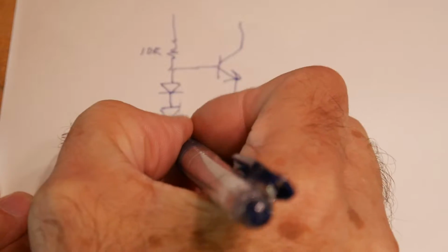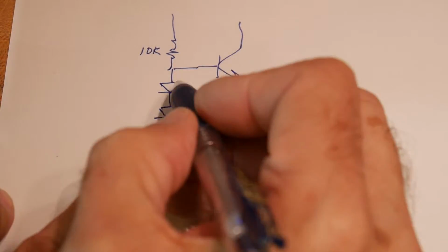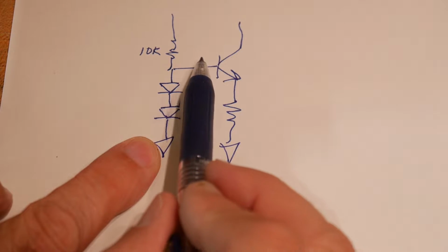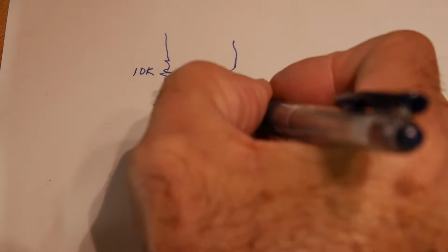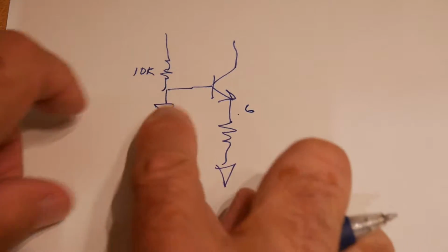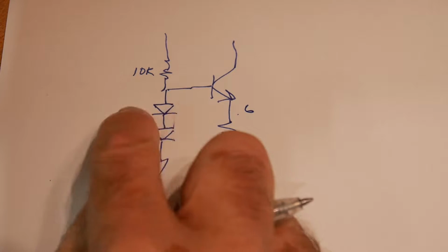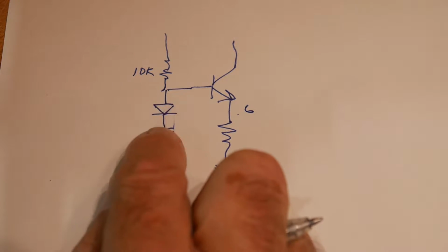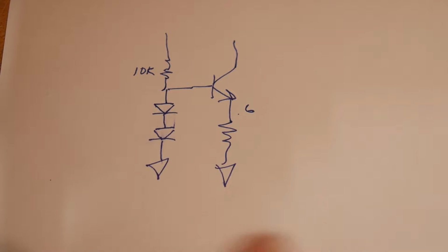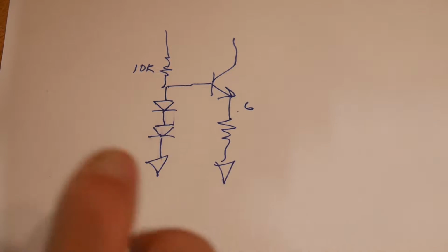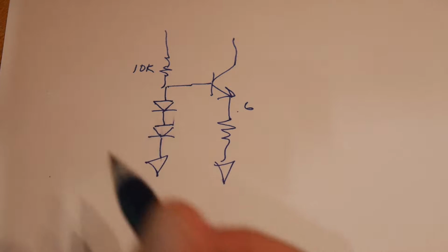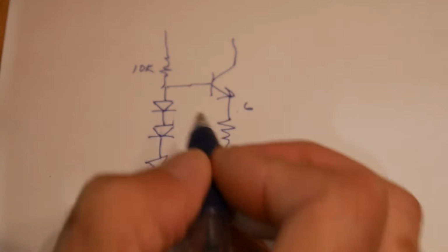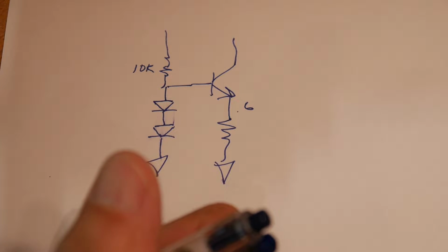So in this particular case, we're going to be putting about 1.2 volts here, or about 0.6 volts here, right, after the diode drop. So one of these diodes kind of accounts for the transistor over here, and then one of the diodes is acting as a voltage reference. We're kind of hoping these diodes don't vary much with temperature or other things. We're using them as poor man's Zeners. We're just trying to create a fixed voltage.